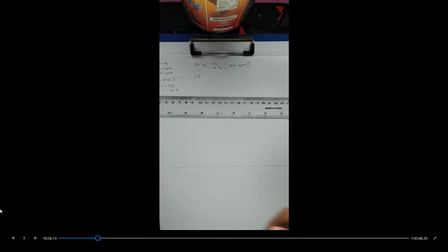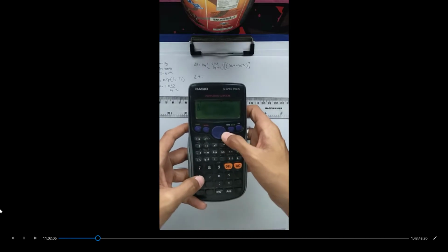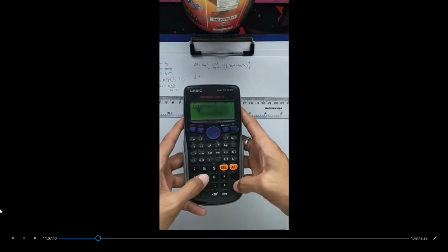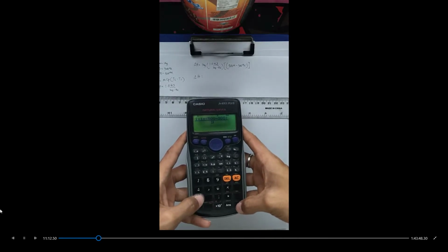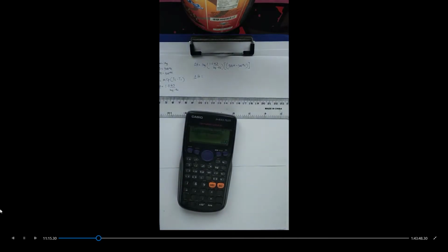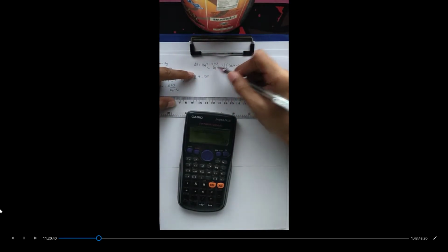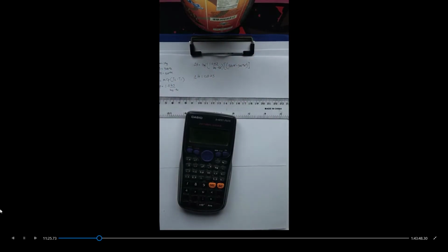By simplifying our constants, at the numerator we have 1 times 1 times the sum 500 minus 300, all over our denominator, which is 1, and so that means our change in enthalpy is 200. Then for the unit, we need to cancel kilograms and cancel Kelvin, so it is in kilojoules. And that's for our problem number 2.